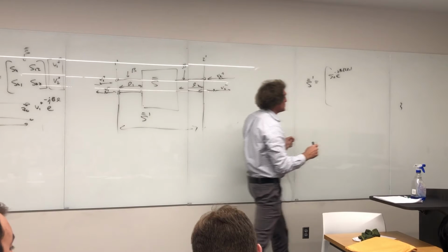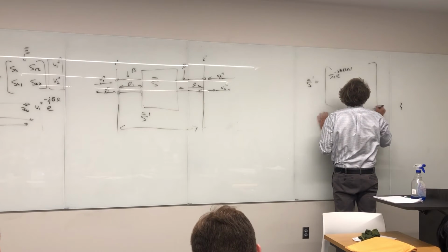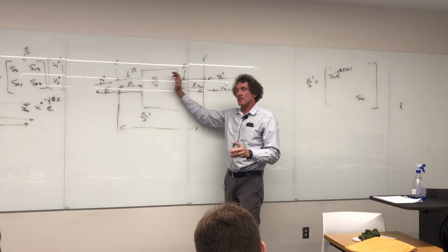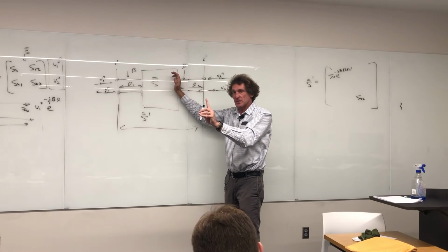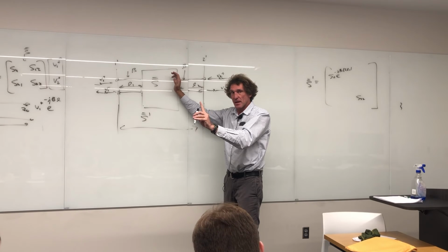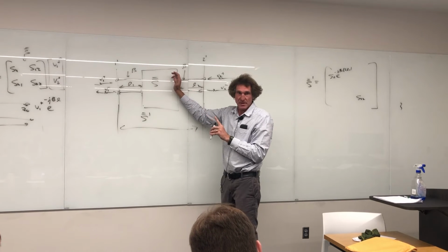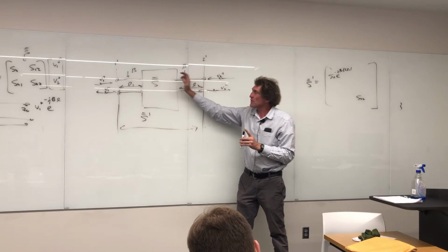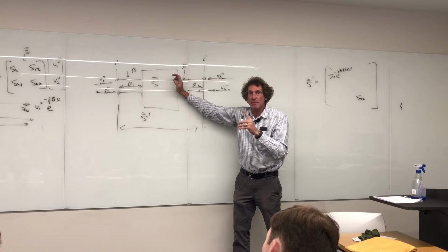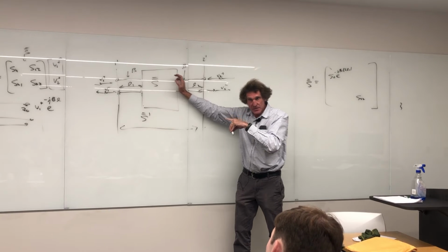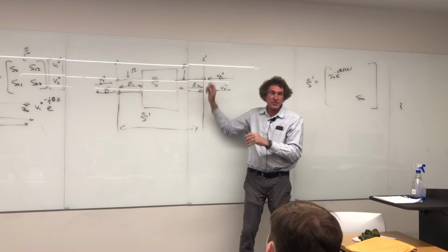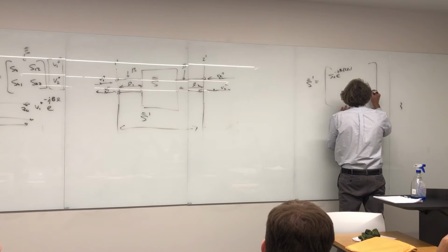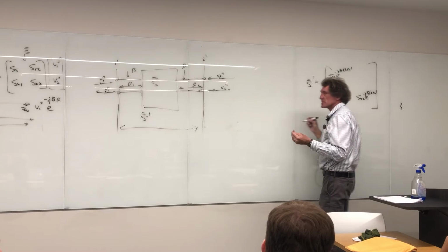Now, when I look at S22 over here, the original S22 is the ratio of reflected to incident signal on port 2, right? Assuming there's no V1 plus coming in. Well, now if it moves back here, the original signal travels first, its phase delay e to the minus j beta L2, and then its phase delay again back when it reflects. So now this is going to have e to the minus j beta, and it's 2L2. Does everybody follow me on this?